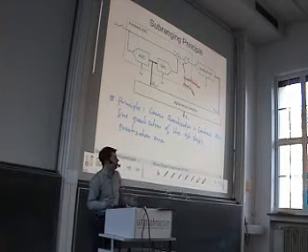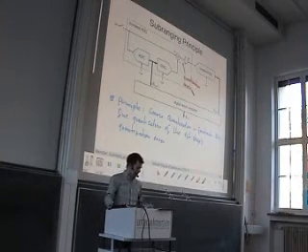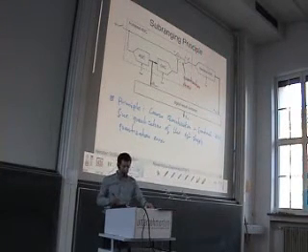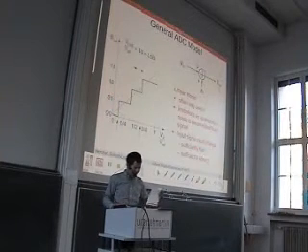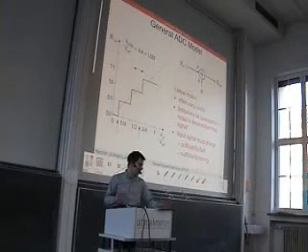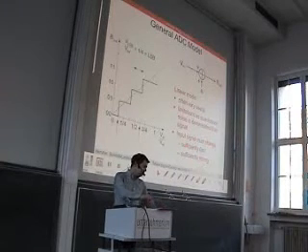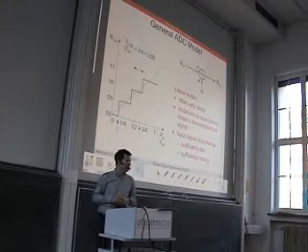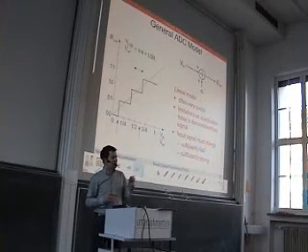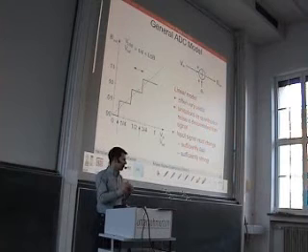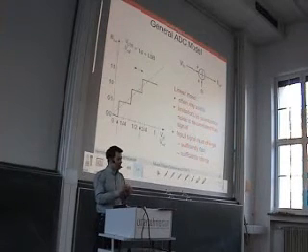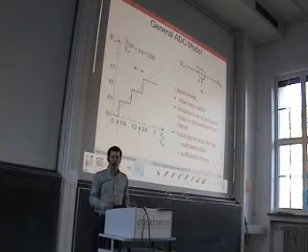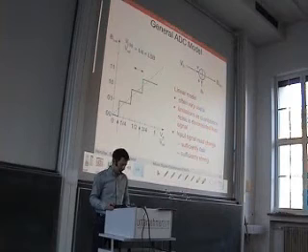And we scale this quantization error back and process it in the backend ADC. Then at the beginning of the ADC chapter, I showed you this slide. And here I said, well, it is not a perfect model, but it's a very useful model to assume that the ADC is something that takes the input voltage and adds some quantization noise to it. And now we will use this model to understand the subranging or the pipeline ADC.